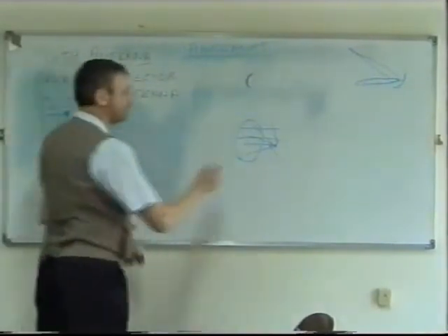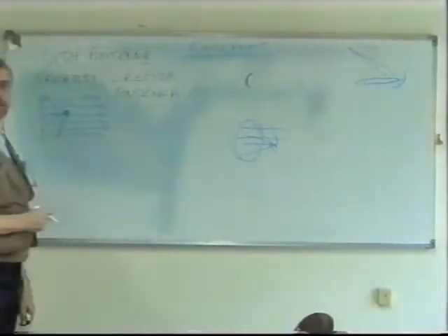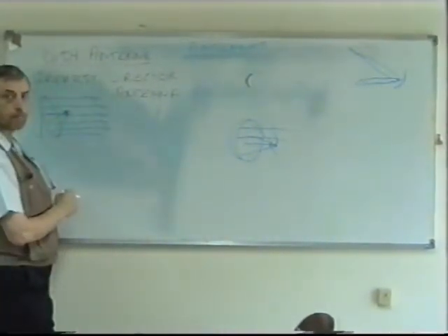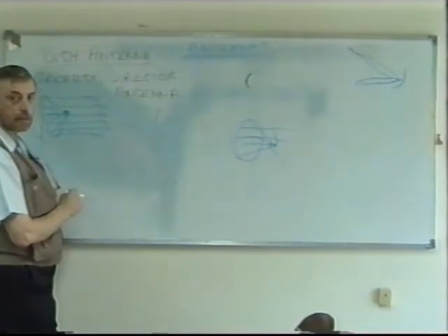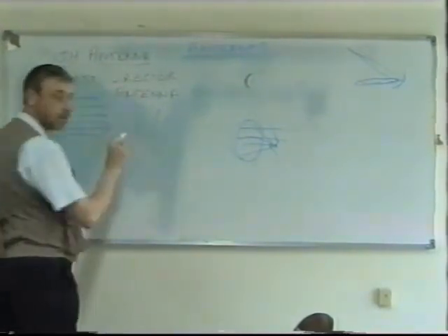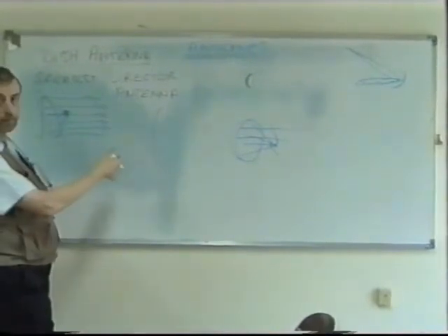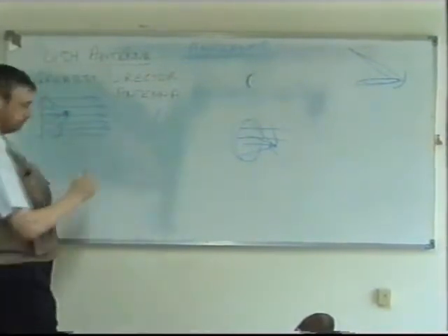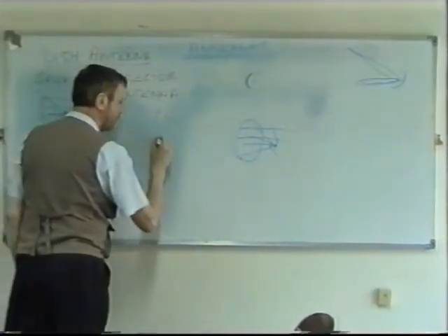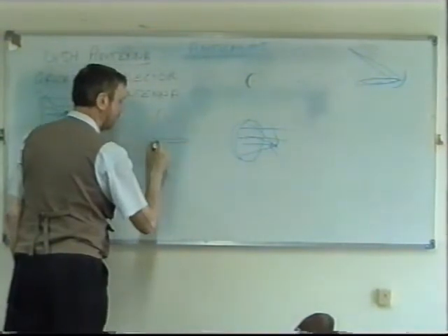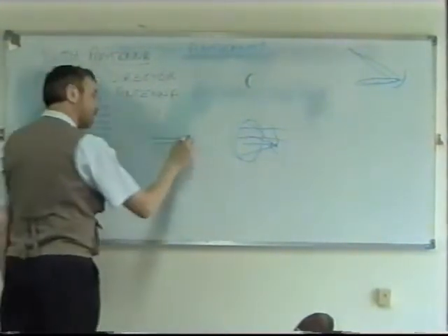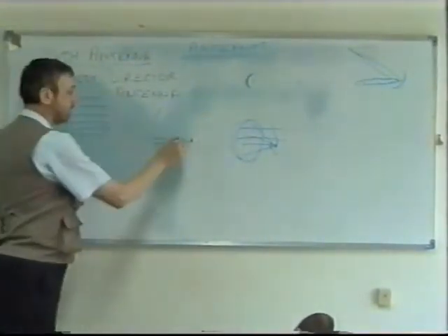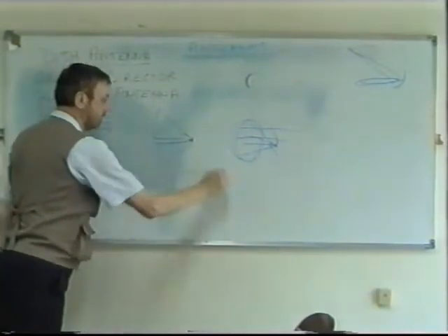The question is, there are 2 or 3 ways in which this antenna can be placed in front of the dish. One way... Can you please repeat the point for why you will get the side lobes? The side lobes, yes. I'm going to explain that with 2 or 3 examples. One way is to drill a hole in the back of the dish and put a metal rod through the hole. At the end of the metal rod we have our little antenna, which can then radiate to the dish and the dish reflects it.